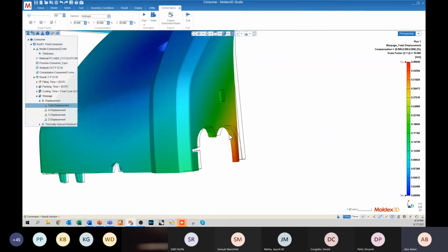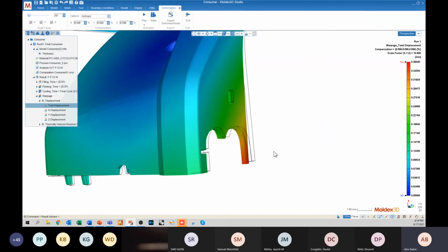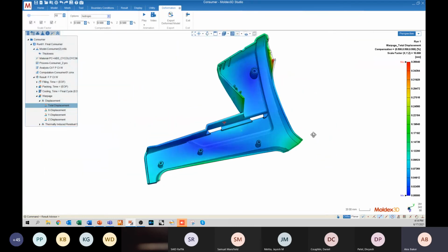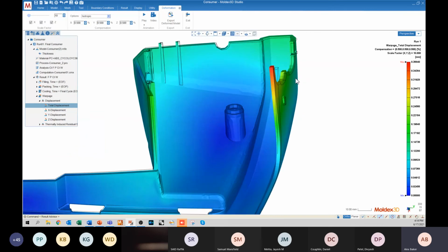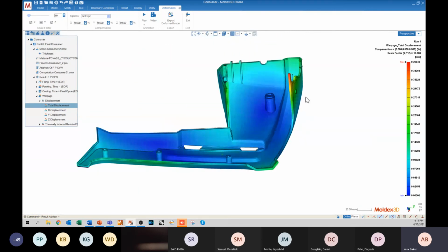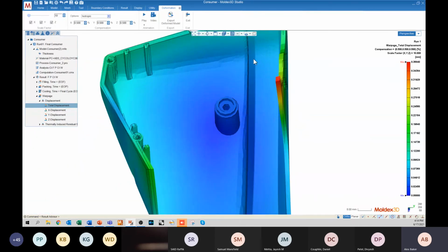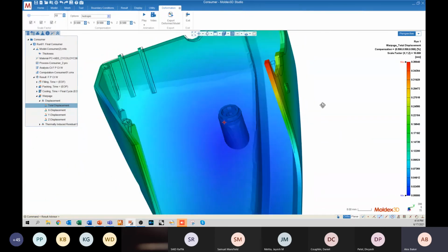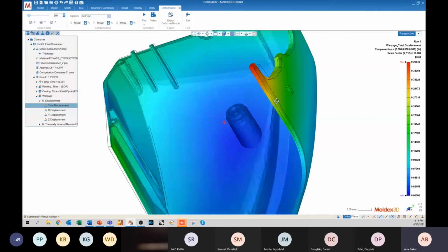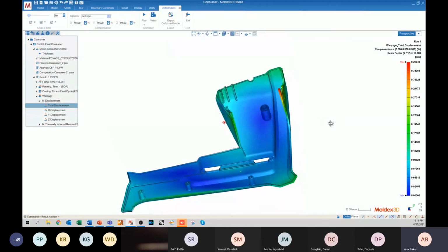whereas this guy down here is still red color. So all that really means is that we've effectively removed the material shrinkage from the equation, and we are just left behind with the warpage. So the regions that are high displacement now are actually warping.